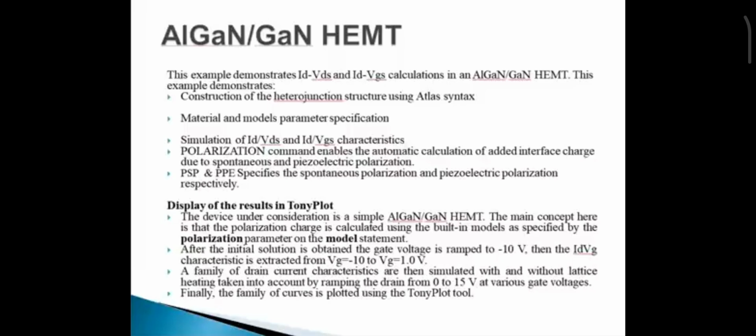This example demonstrates construction of the heterojunction structure using the FS index. Second one, material and model parameter specification. Third one, simulation of ID versus VDS and ID versus VGS characteristics. Fourth one, polarization commands enable the automatic calculation of added interface charges due to spontaneous and piezoelectric polarization.